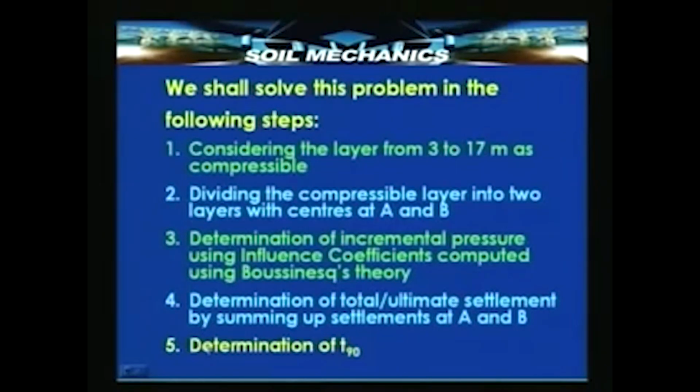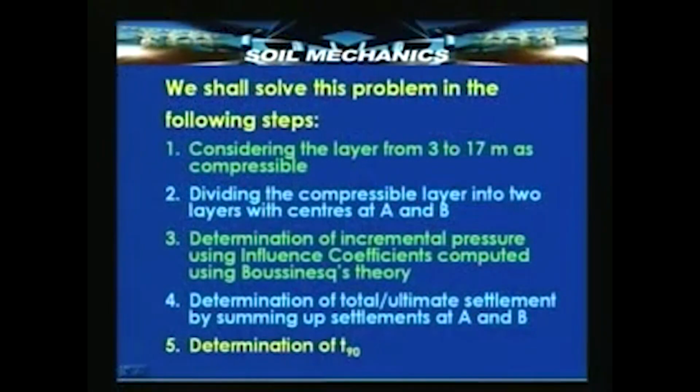We shall solve this problem sequentially. Now, what are the typical steps which are involved? Number 1 is identifying the compressible layer, which I have just now mentioned. 3 meters to 17 meters is the thickness; 14 meters is the thickness of the compressible layer.